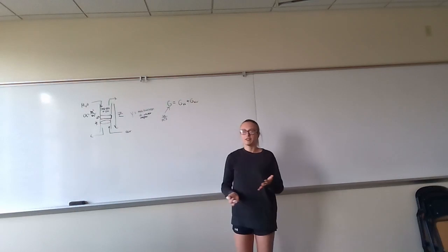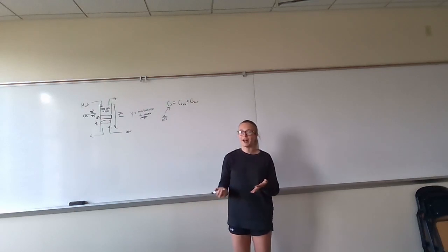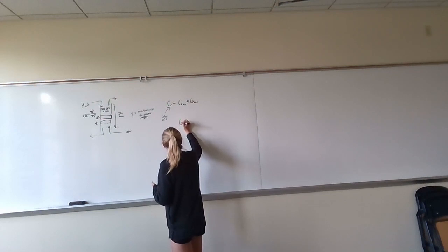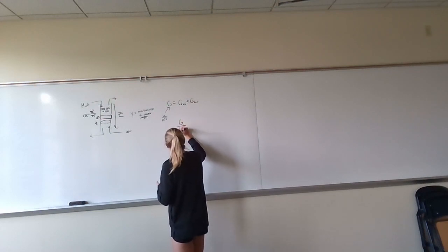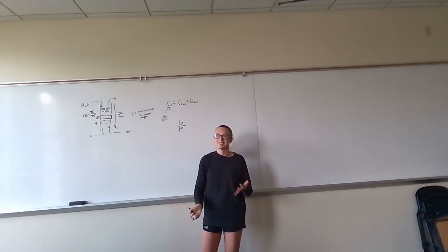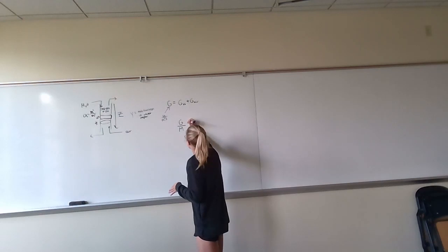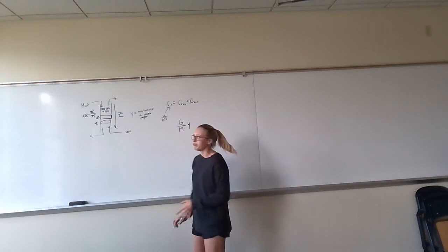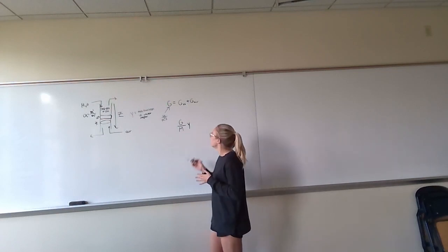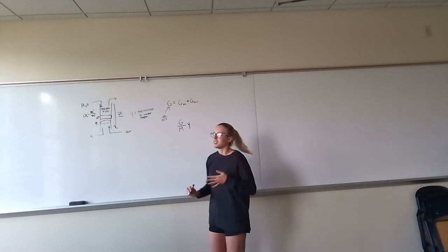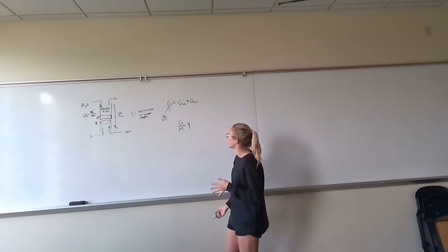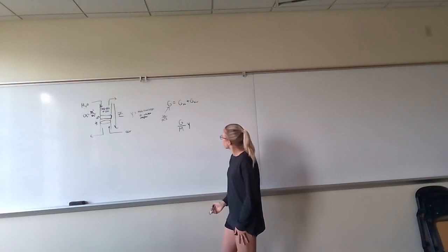So when looking at the change in mole fraction, we know that the total gas flow rate divided by the molecular weight gives us moles per meter squared seconds. And when we multiply this by the mole fraction of water, we get GW, which is the flow rate of the water vapor in the gas phase.